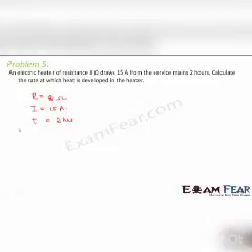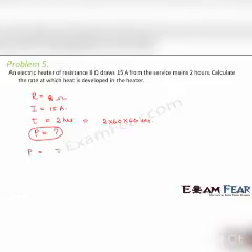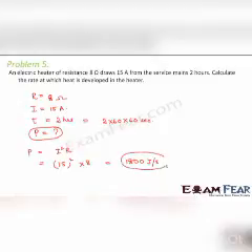And what is the rate at which energy is consumed? That is nothing but power. So that means we have to calculate power. Now convert this time into seconds. It will be 2 into 60 into 60 seconds. Now, how do we calculate power? We know that power is given by I square into R. So we really don't need this amount of time for which it takes this much of energy. So power is I square R. So I square is given as 15 square into R is 8 ohms. So this comes out to be 1800 joules per second. So this is the rate at which heat is developed in the heater.